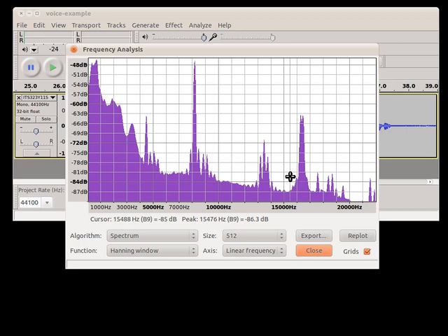3 dB is a factor of about 2 in the absolute measurements. So in fact, this signal compared to here, although it doesn't look like much compared to the rest, this is a factor of 16 times weaker. That is, the signal at this frequency component, around 2 kilohertz, is 16 times smaller than at about 500 hertz.